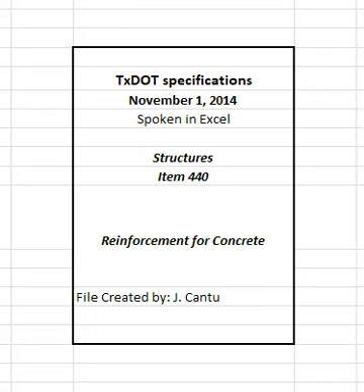The exposure of the ends of longitudinals, stirrups, and spacers used to position the reinforcement in concrete pipe and storm drains is not cause for rejection. Tie reinforcement for bridge slabs and top slabs of direct traffic culverts at all intersections, except tie only alternate intersections where spacing is less than 1 foot in each direction. Tie the bars at enough intersections to provide a rigid cage of reinforcement for reinforcement cages for other structural members. Fasten mats of WWR securely at the ends and edges.